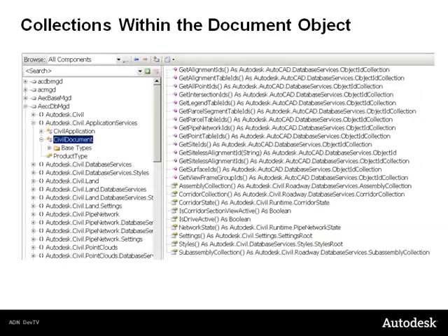The document object not only contains collections of AutoCAD Civil 3D drawing elements such as points and alignments, but also objects that modify those elements, such as styles and label styles. Collections in CivilDocument are ObjectId collections for most objects. Objects in this collection must be retrieved with the Transaction.GetObject function and cast to their type before they can be used.